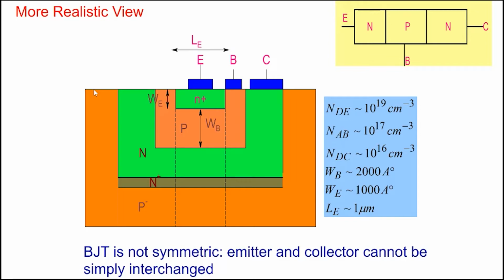So let's say you have a silicon wafer which is p-type doped, and in this wafer you diffuse n-type impurity and then p-type impurity and then a heavy impurity, n plus, here. So this is the n-type, this is the p-type, and then this has become n-type, and there is an n plus region here to provide a low resistance path to the contacts.